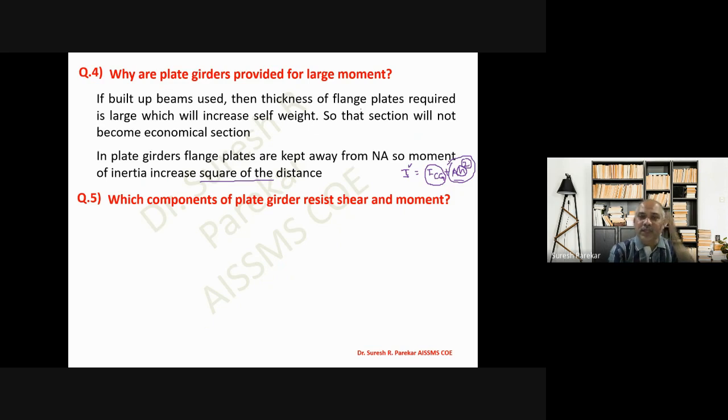Then which components of plate girder resist shear and moment? Generally we have the assumption that the flanges of the girder resist bending moment and the web resists shear.